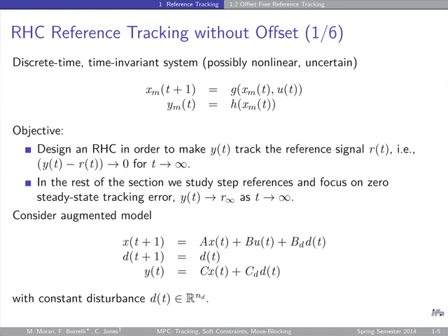So what's the dynamic model of a constant disturbance? That is here: d(t+1) = d(t). So it doesn't change, it's the same. That's just a model for a constant input. And we will not know this constant input. That's some disturbance that happens to affect the problem, but we don't know it. And so what we want to make sure is that we can get a correct tracking of this y even when we don't know the disturbance.